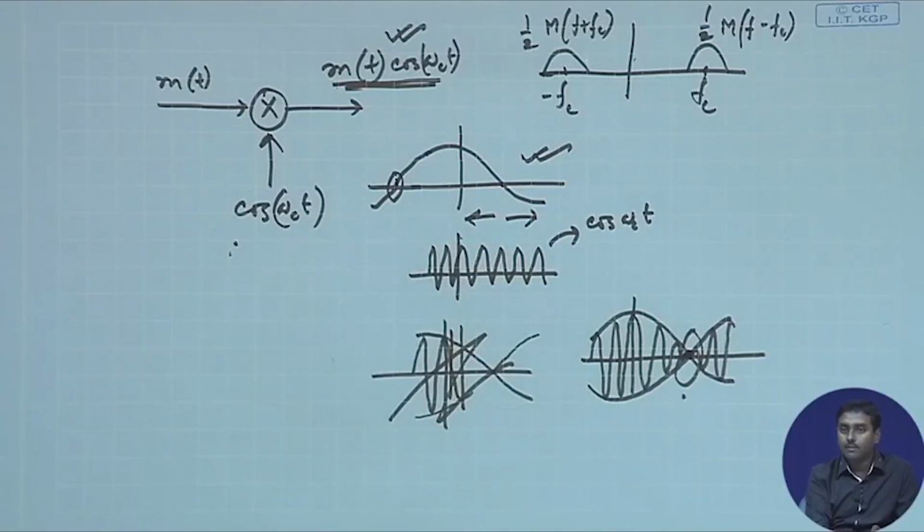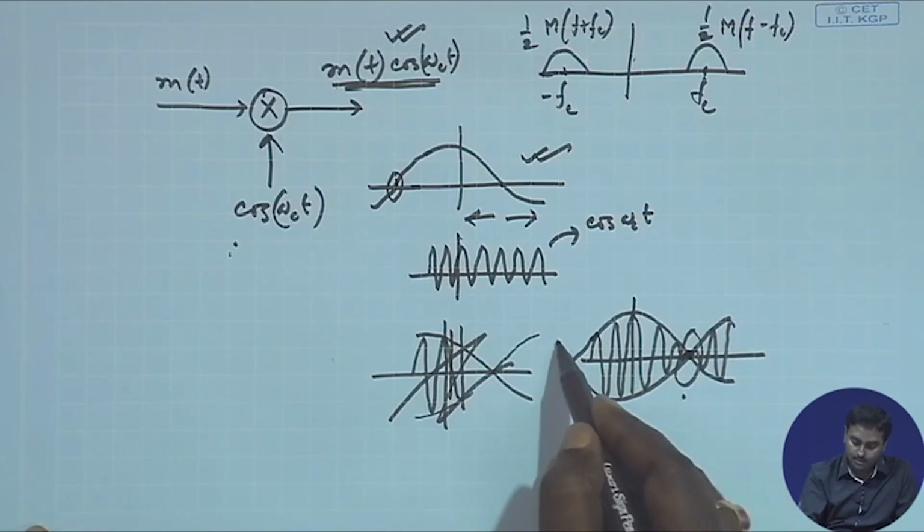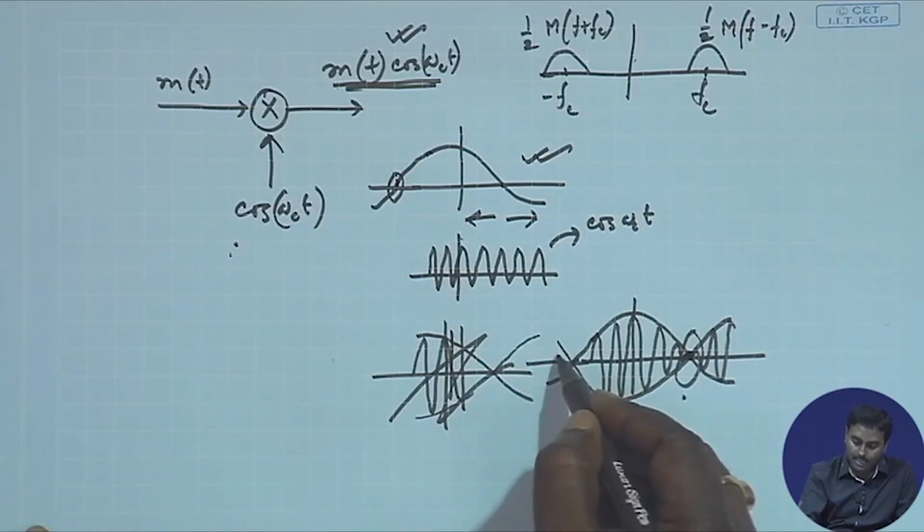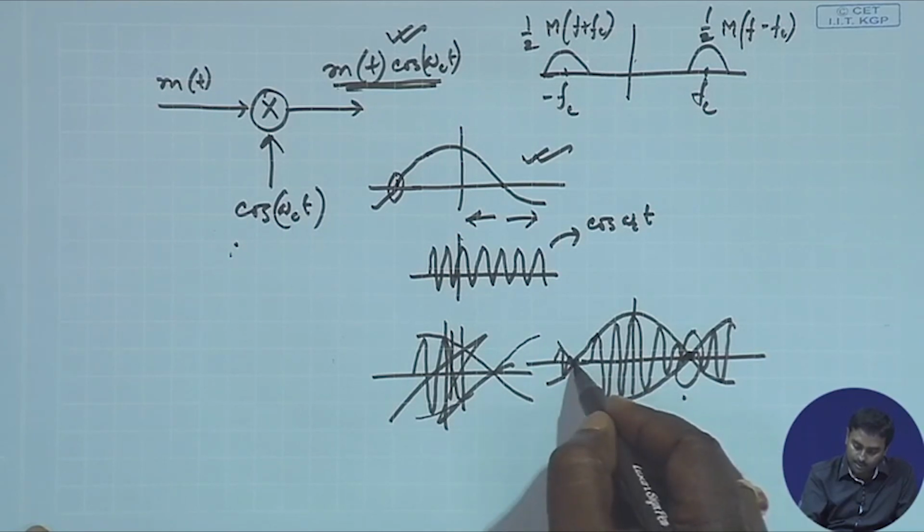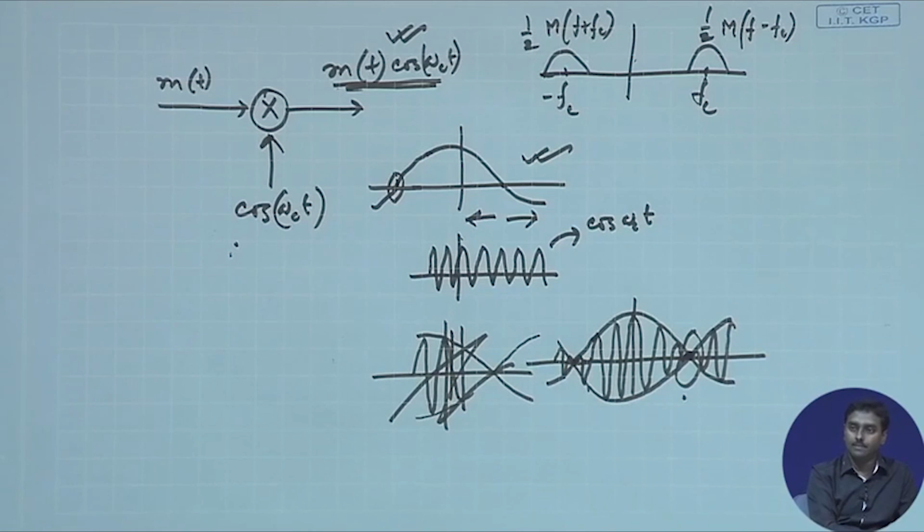But from the time domain, we are just trying to analyze whatever is happening. Okay. So, as many times as there is a zero crossover, that many 180 degree phase reversals will be happening. If this also had a pattern like this, there also we would have observed a similar thing. The envelope will be just like this, and again if things came out like this, there will be a 180 degree phase reversal immediately. So, as many zero crossovers will be happening, that many phase reversals will be happening. So we have understood what the modulation is, right.